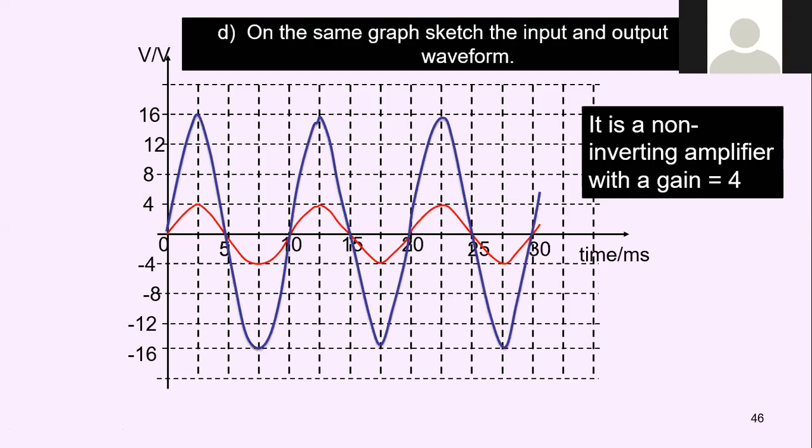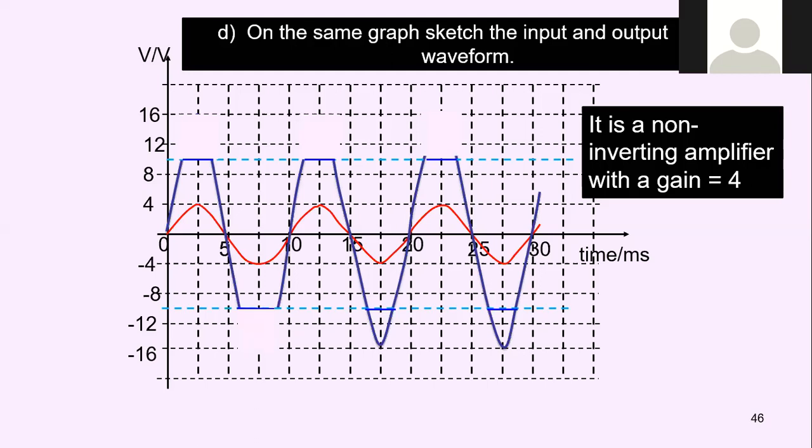Then remember, our supply voltage is just 10 volt only. So it means that it will cut off, which is the clipping effect, or saturation. At 10 volt you will just cut off, so you won't see the original waveform. That's what I mean by clipping effect. 10 volt is somewhere in the middle there. Too high again.